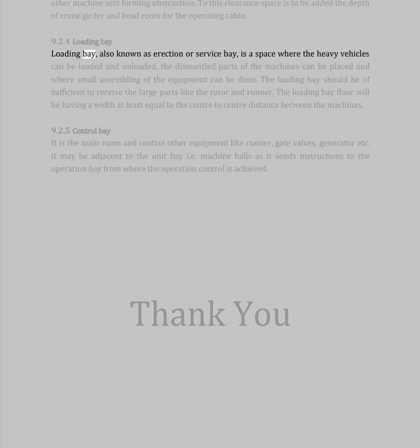9.2.4 Loading bay, also known as erection or service bay, is a space where the heavy vehicles can be loaded and unloaded, the dismantled parts of the machines can be placed and where small assembling of the equipment can be done. The loading bay should be of sufficient size to receive the large parts like the rotor and runner. The loading bay floor will be having a width at least equal to the center-to-center distance between the machines.